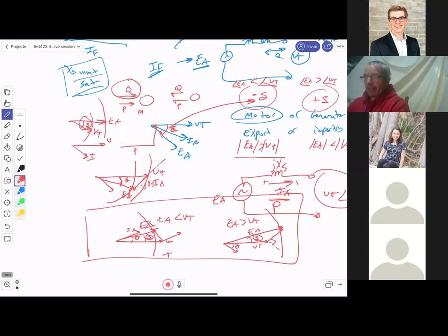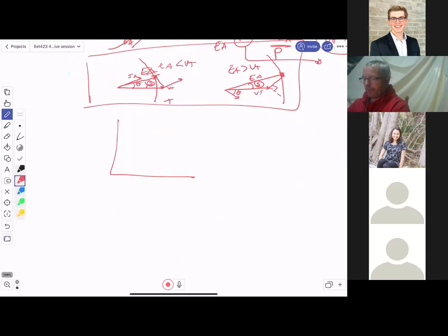And I think the last thing that we talked about, we did all the testing, right? We did the saturated, unsaturated. We should be able to go back and forth and be able to calculate impedances, whether it's saturated or non-saturated. How can you tell if you're saturated or non-saturated? Well, remember, here's our open circuit characteristic. Here's our air gap line. So this is the air gap line, and the saturated characteristic, open circuit. The air gap line basically just does this. So you can tell where you are.